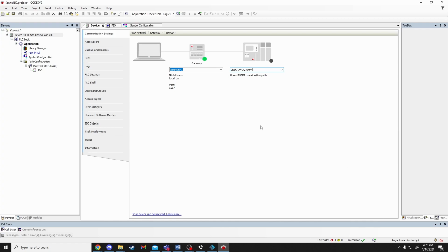There are 2 pieces of software running right now for CODESYS, technically 3, but we're going to ignore the gateway side. The other piece of software is in your tool tray here. So we see this little cube. This is our gateway. And this little cube here, the 64, that might say 32 if you're on the 32-bit. If you right-click that, we can click Start PLC, and now our device is active. It's active on our network. There we go, it lit up.